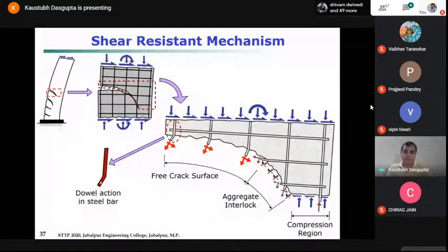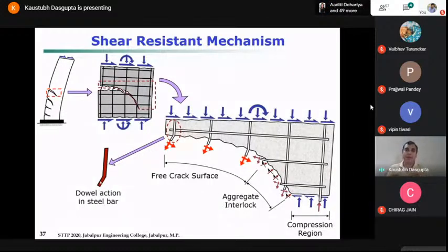Now these steel bars are very stiff. Okay? Basically, if you look at the minimum diameter of the steel reinforcement, in columns it is prescribed as 12 millimeter. The same criterion is applicable for walls as well. So the minimum diameter is 12 millimeter. So a 12 millimeter bar, if you try to bend it like this, requires quite a lot of effort. If you go on increasing the bar diameter, it becomes very difficult to bend, right? That's why larger diameter bars, you cannot bend manually. It needs a machine. Okay, so this dowel action also helps in resisting that sliding movement to a considerable extent.